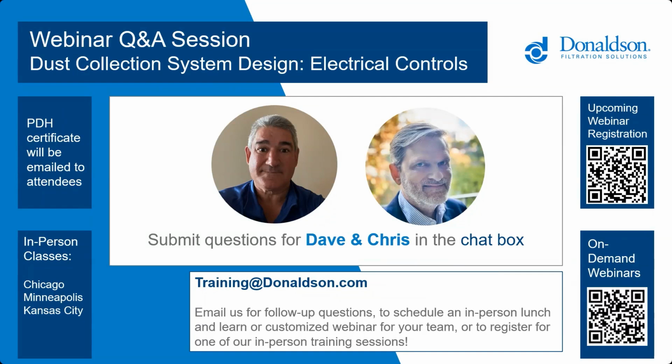If people are going to be welding every day, a more permanent solution is required. Yep. I would say be careful. Again, combustible dust is the main issue. You typically don't want to run a portable dust collector on a combustible dust because if you would have an explosion, it becomes a rocket. So you just think of it that way. Just think about, you just don't want to do it.